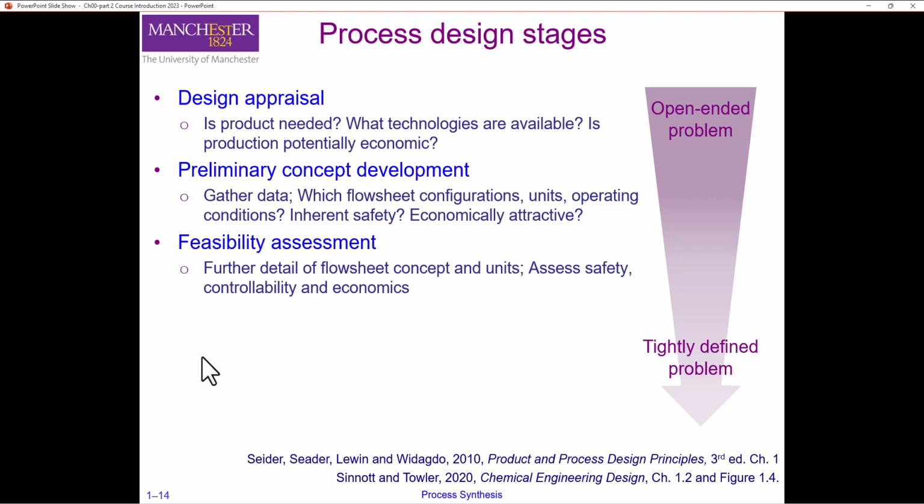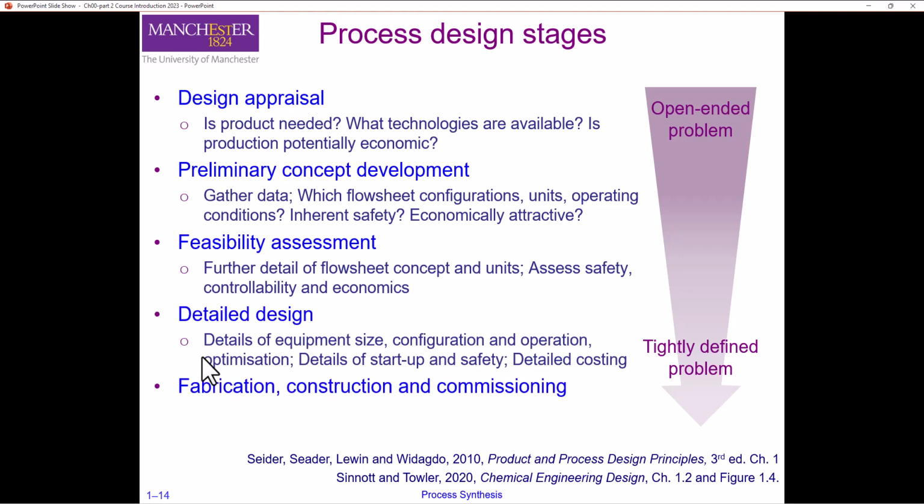And finally, it looks at the economics of the project. So is it possible that the process being designed could be economical? Remember that at this stage, we have little information beyond what the raw materials and the products are going to be. However, a negative answer to this question is helpful for making a go/no-go decision to avoid spending any more time and resources in design activities.